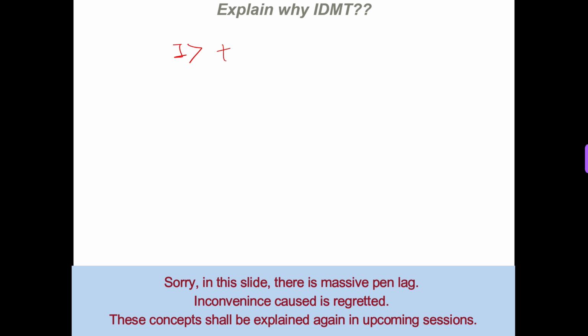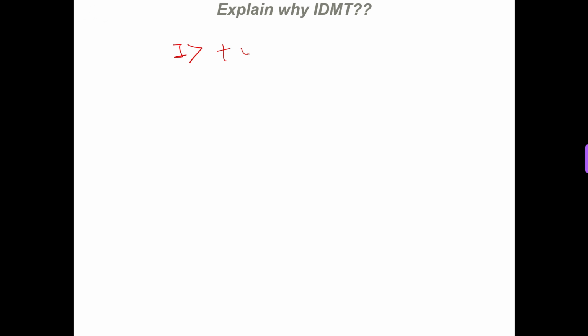Whenever there is a flow of current, suppose this current flows for time t, then you have a rise in temperature. Every electrical device has some insulation, designed for some level, and that insulation has its property. When the temperature rises and after some time crosses the thermal limit of that particular device, then the device is going to fail. So that is one condition, thermal.